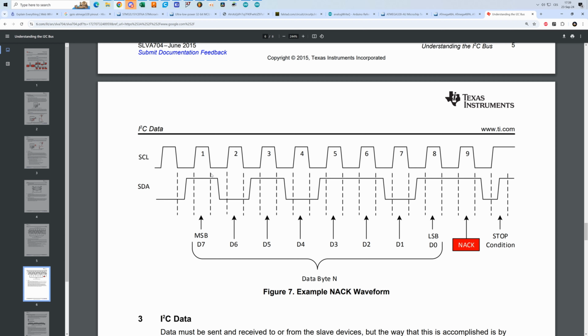Now in another clock period, we are going to look at what is the state of the bus when the serial clock goes high again. So on this rising edge, we see a 0. And then again, rising edges. Over here, we see 1. So this is 1, 0, 1. This would be 0. This would be 1, 1, 0, 1, 1, 0. So this is how the serial communication on the I2C bus works.